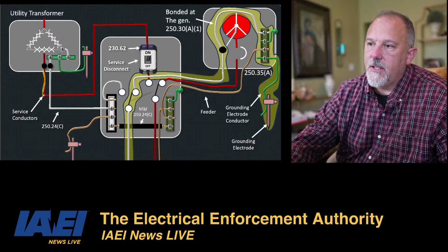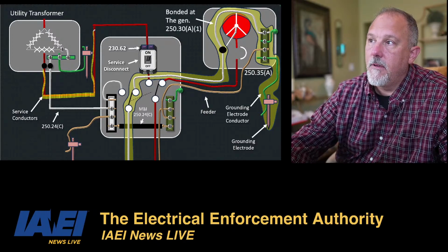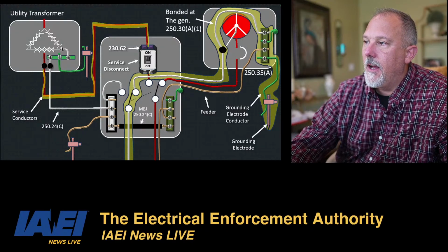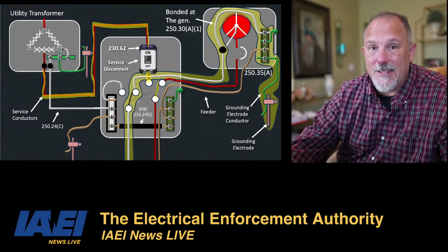So all of this is my utility side. All of this, when I'm on the generator, I have no connection because I have switched the hot conductor too.